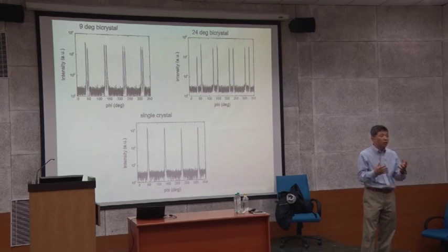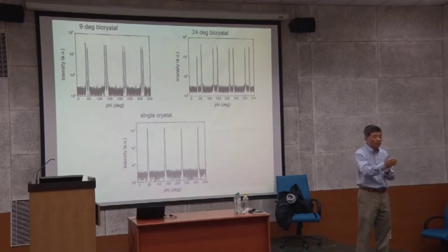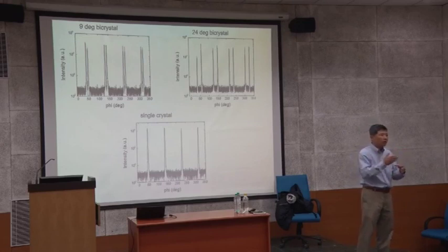Once you get the structural characterization, for example, okay, I have strain along that direction and this direction, you can pattern your sample into a measurement bar, a 4-point measurement bar, along a particular direction for applying electric field and magnetic field. You have to do anisotropy measurements of your single crystal epitaxial thin films.